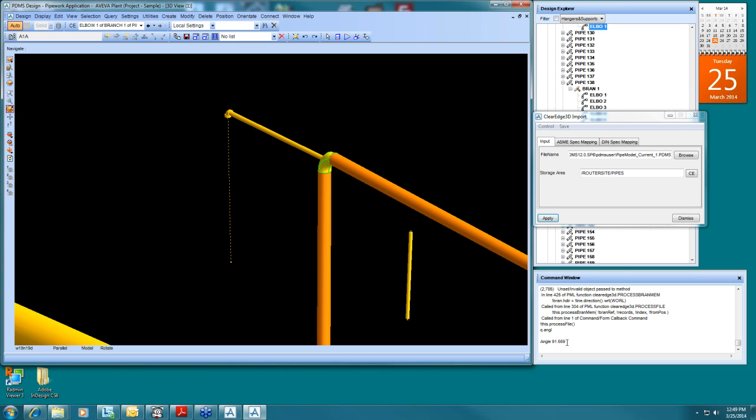In PDMS, you cannot bend the pipe or anything like that. You would have to go in, if you want to clean this up, at the end of this socket weld elbow, you could put a zero-length variable angle bend, like we do for slope piping in PDMS when we model it, and have that directed towards the pipe tail and have the implied tube come in at that point.